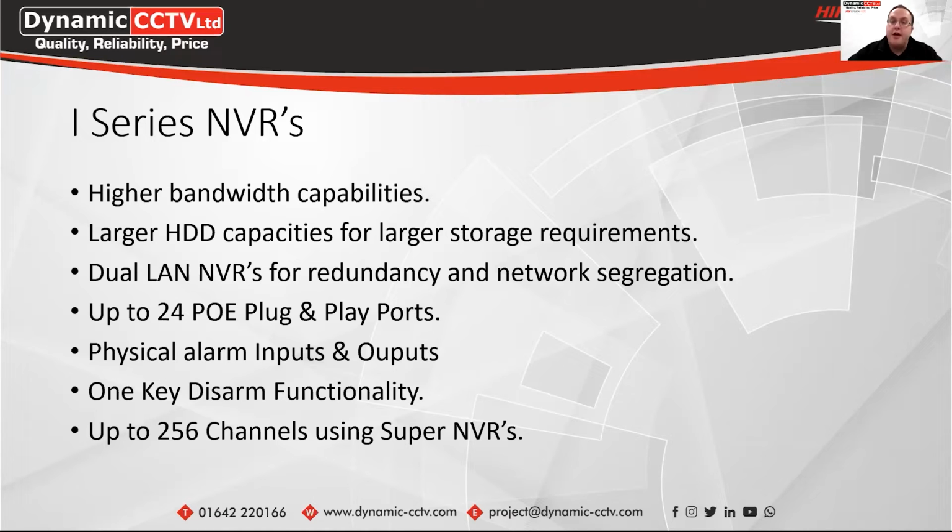So this is perfect for monitored sites when you're using monitoring stations, instead of relying on schedules for your arming and disarming. With the I series, it has the one-key disarm function ability, which you can enable on the alarm input 1 on the NVR itself for the actual system there.